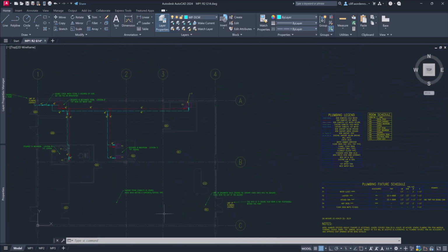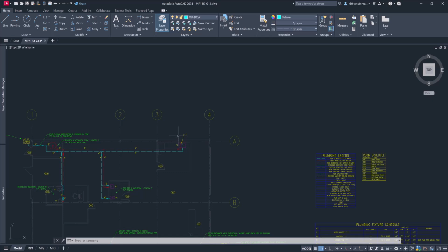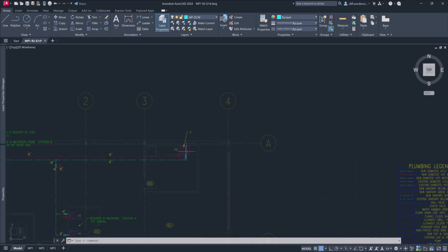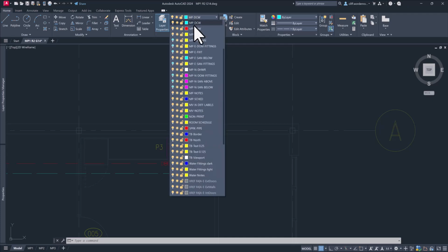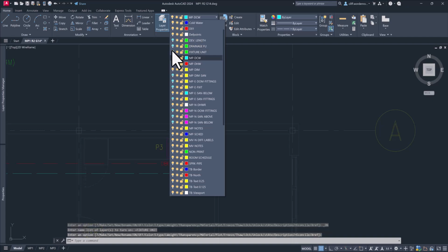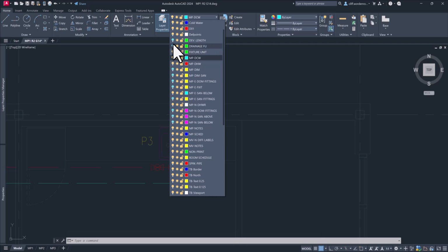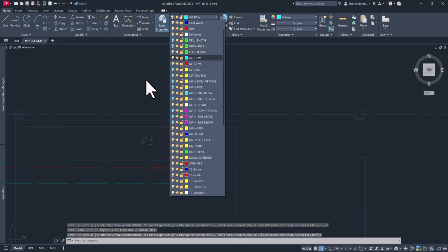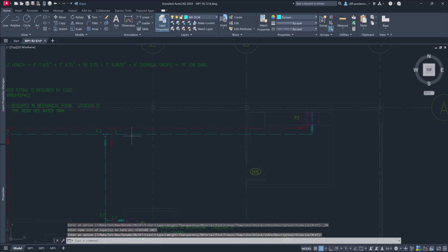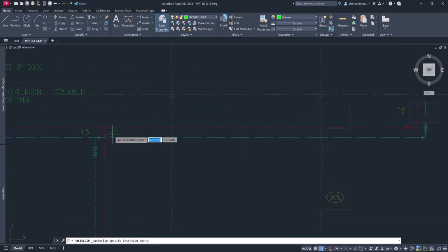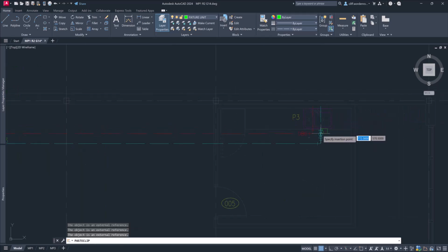So again, you start at the furthest location away, right? It would be this one again. So this, for fixture units, let me turn all that off. I must have deleted that. Weird. Okay. So again, I'm going to have 3 fixture units on my cold. So I'm going to paste that twice. So there's 3 hot, 3 cold. All right. 3 fixture units.